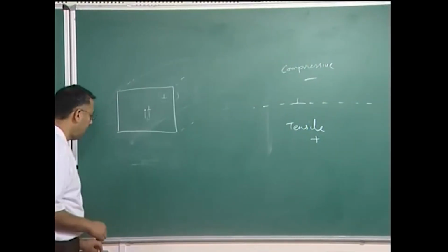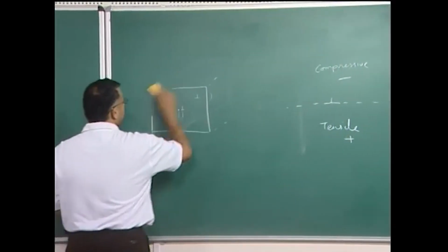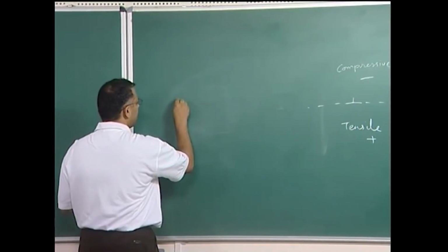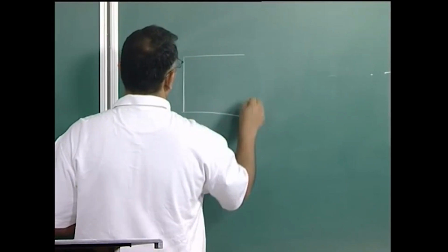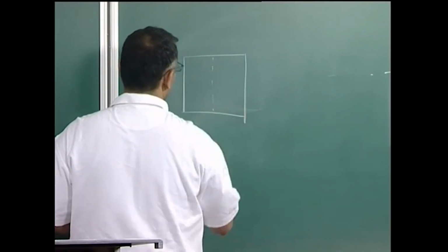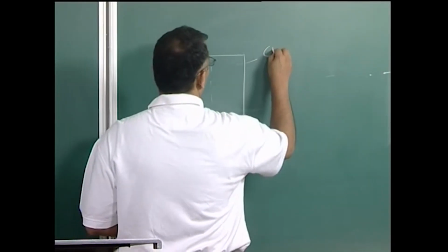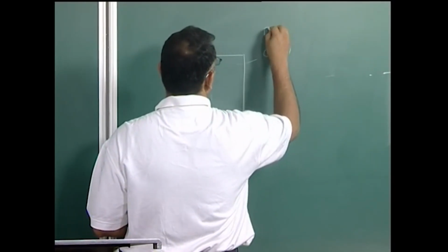Now, regarding splitting of partials, suppose I have a crystal and now I am drawing the slip plane in this crystal. So, this is my slip plane in the crystal and I put a dislocation. Let me now consider this to be the 111 plane in an FCC material like aluminum.